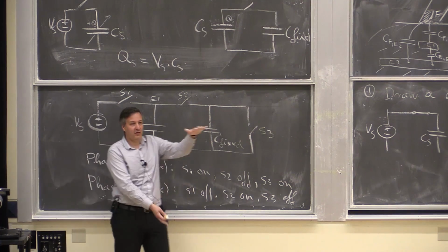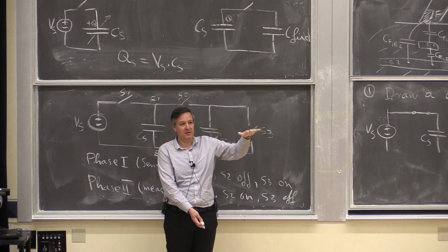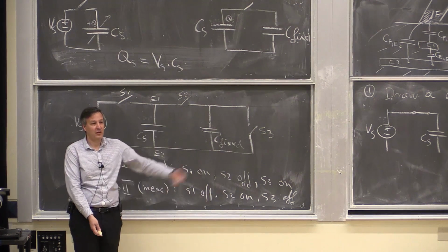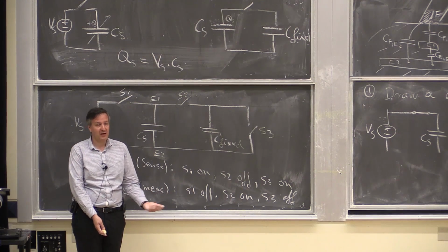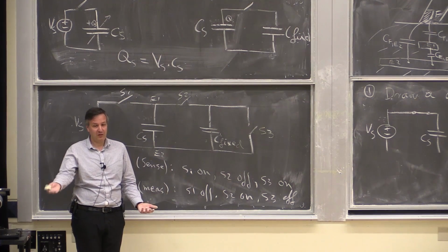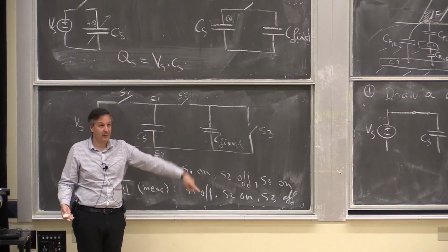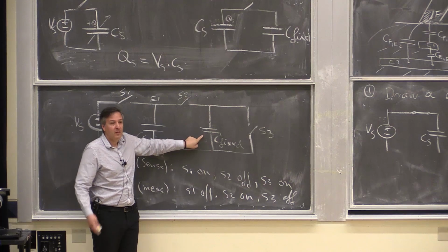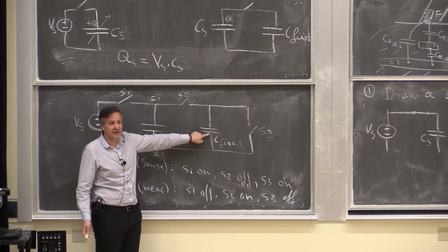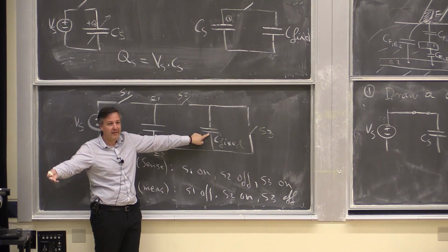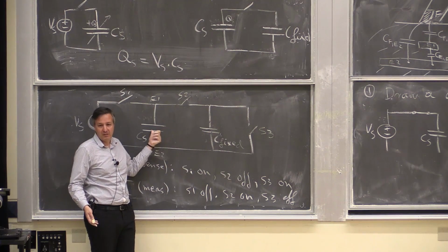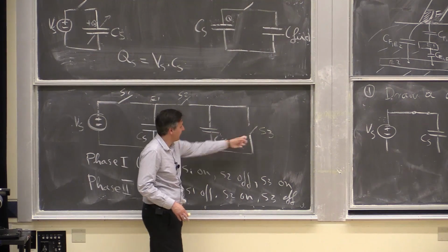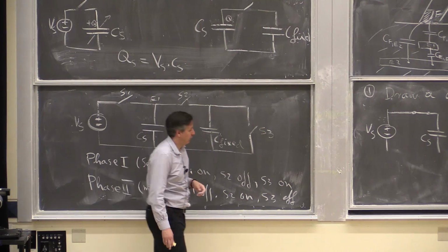So imagine I have a bucket full of water that's at some level that I want to find out. And here I have an empty bucket. When I share them, I will know exactly what voltage I'm going to get. That voltage will represent that sensed charge, Q sense. But now, if there's some residual charge sitting here from a previous cycle, then I no longer know what was the change here, because there's a little bit of error there. So that's why before every sharing cycle, we zero out that voltage.